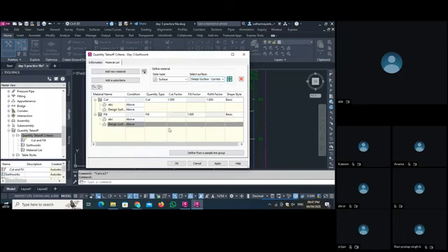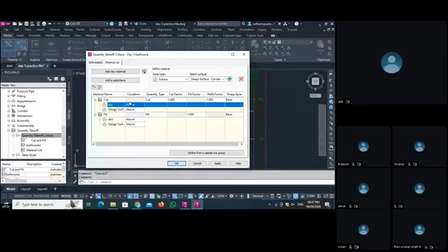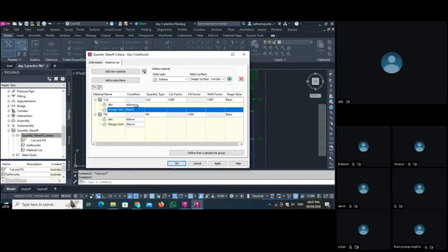Now I want to calculate the earthwork. In earthwork, we calculate the cut and fill criteria. So I want to see how much cut is there, how much fill is there. So for that, we have to make sure you play with this condition. If your ground surface is above, then you make sure your design surface is below the ground surface. So once this condition is set, then only the cut criteria works.